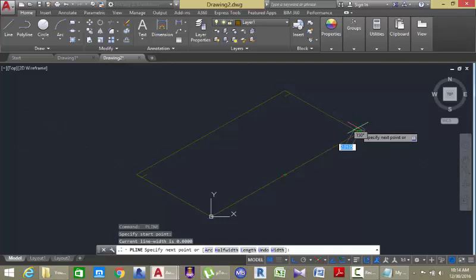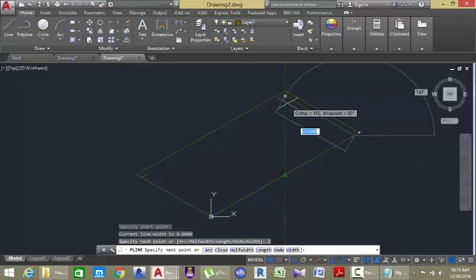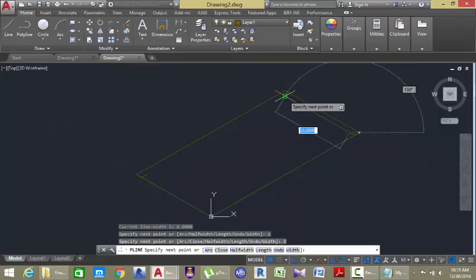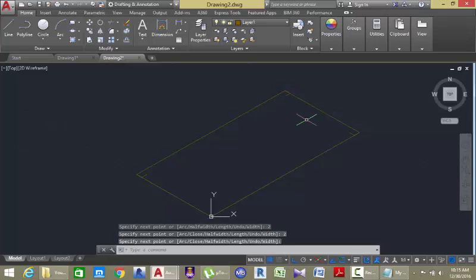Now the first point that I snap on this. So if I snap this point, whatever units I enter will override the current unit, but it maintains the orientation of the line. So now I'm going to enter 2 units, press enter, move the mouse cursor to this direction, then maybe snap to this point and enter 2 units, press enter again to end the command.